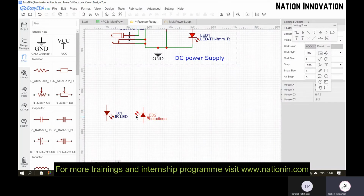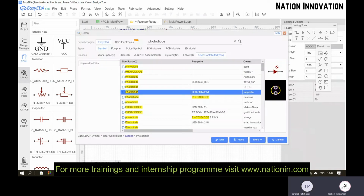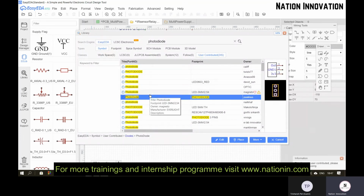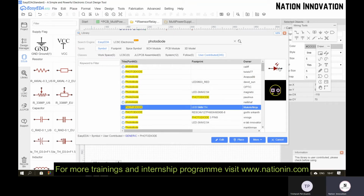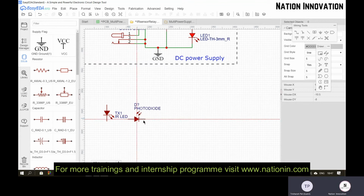Actually, the photodiode receives the IR LED's light, so the arrows should be facing towards this component. Let us find that. It is the correct symbol, but it has no footprint here. You can select this one. It has both footprint and symbol. Okay.